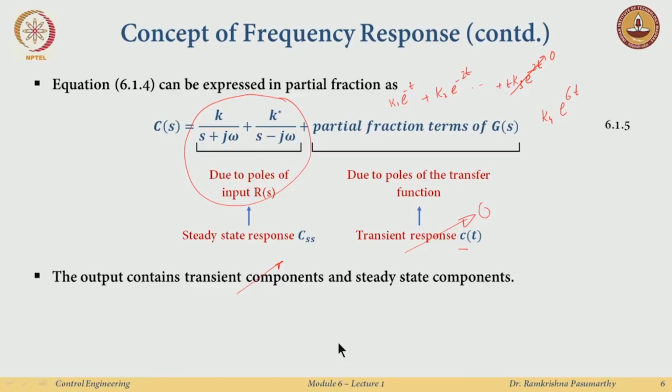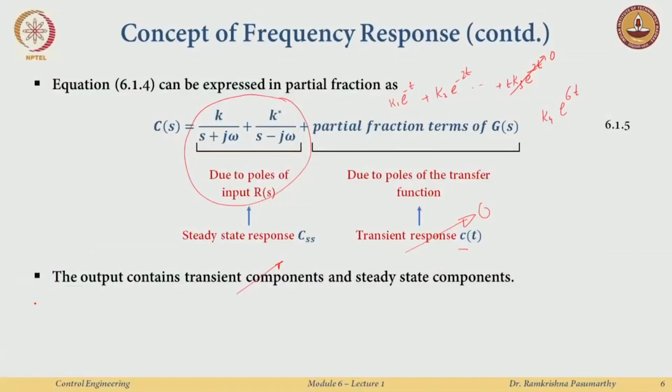Okay. Now, what is this response at steady state when the input is a sinusoid? If you look at the earlier analysis, in the step response, even though we had oscillations in the system, those oscillations were dying down. So, if I just take an underdamped system, we had a response which was like this for the step response, and you see there were still oscillations, but they were actually going down with time. So, there you had terms like e power minus t cos omega t and so on. So, whatever frequencies we had, the oscillations just die down, and whatever remains after these things go away is this.